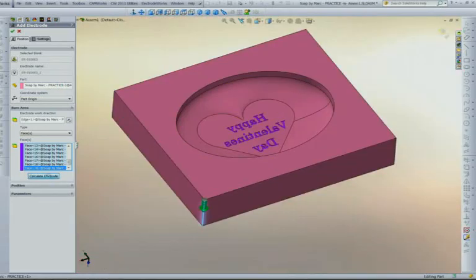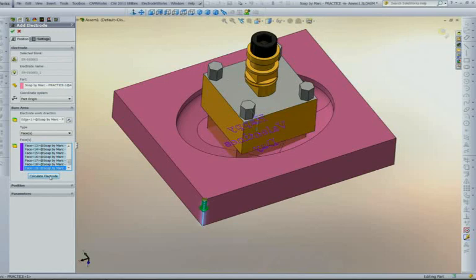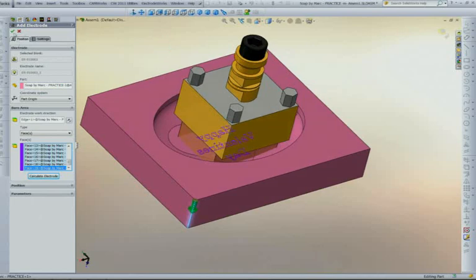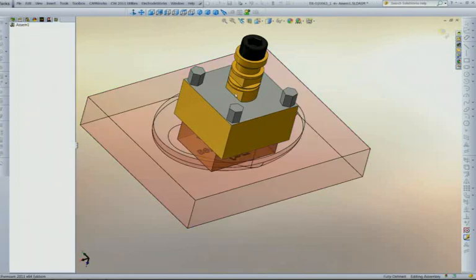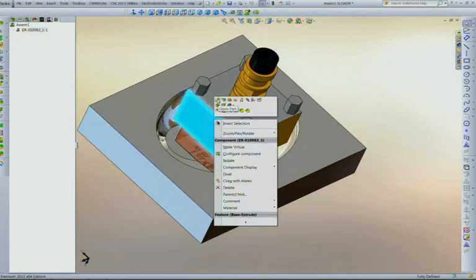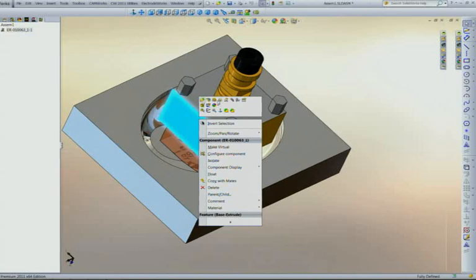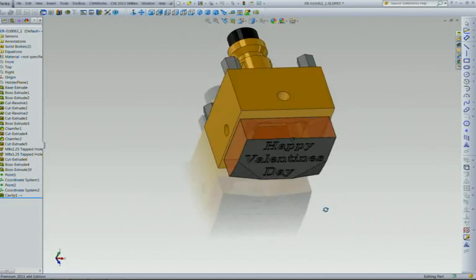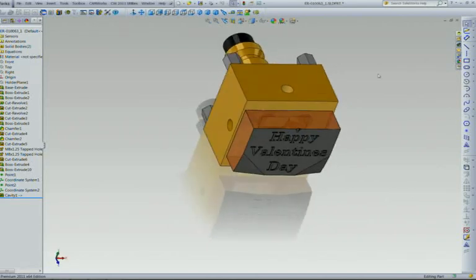let's back out a little bit here and say Calculate Electrode. And the electrode is automatically created by ElectrodeWorks and added to my SolidWorks assembly. This looks great. Okay. The electrode becomes a part, or component, in the assembly, and I can open up that part and look at and edit the electrode as well. I might mention at this point, too, that I could also add spark gap or clearances, and it will automatically offset the geometry for me, for example, for the spark gap.